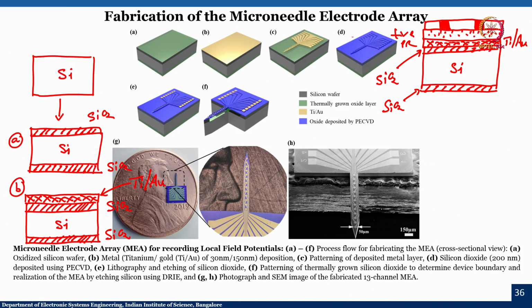So, this one will be your bright field mask. After that, for positive PR you have to do soft bake, load the mask, and then expose with UV light. After that you unload the mask and develop the wafer.